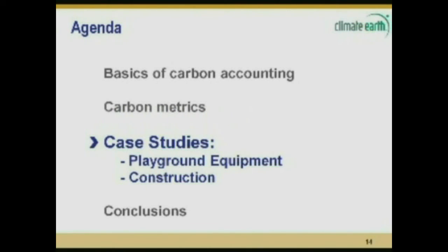And let's see, the other question was, how is carbon output for cement measured? In this case, we used a combination of the Climate Earth database, which gave us industry averages. I'll show you more specifically that. And then we went directly to the supplier, in this case a couple of suppliers, and measured their direct emissions to calibrate and differentiate between suppliers.